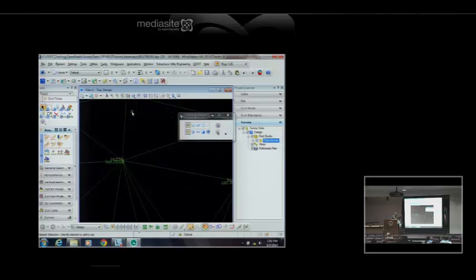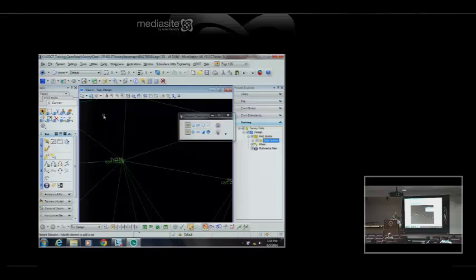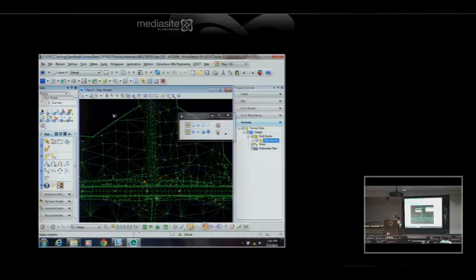The annotations themselves, again, are all on levels, so I can turn off that level. Over here on the left under the tools, there's a survey group of tools, and I'm not going to go through all these tools, but one of the ones that's kind of nice is one to turn off the annotations, so you can just toggle them all off. Let me change my feature display. Well, I'm going to leave it that way for now.